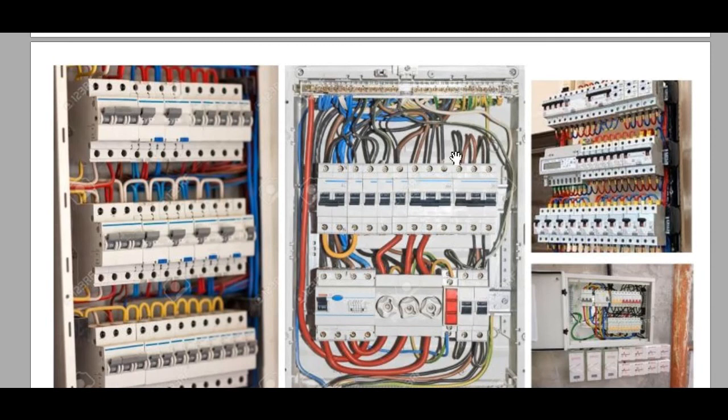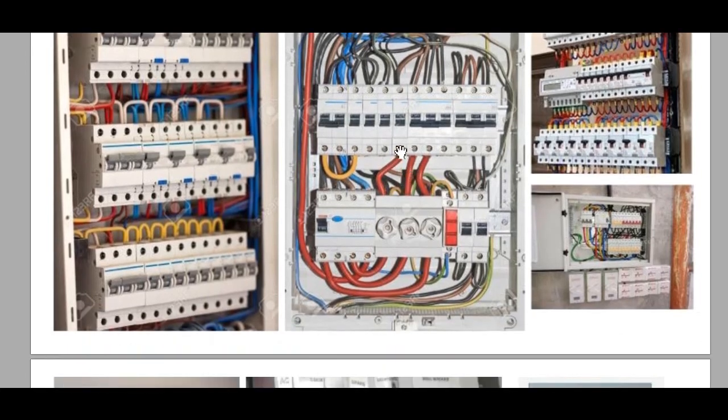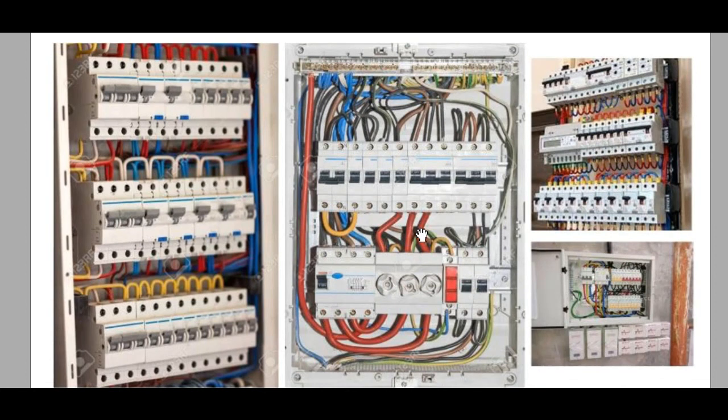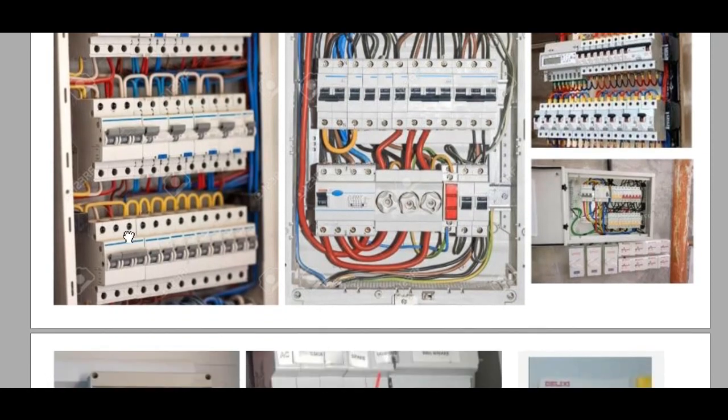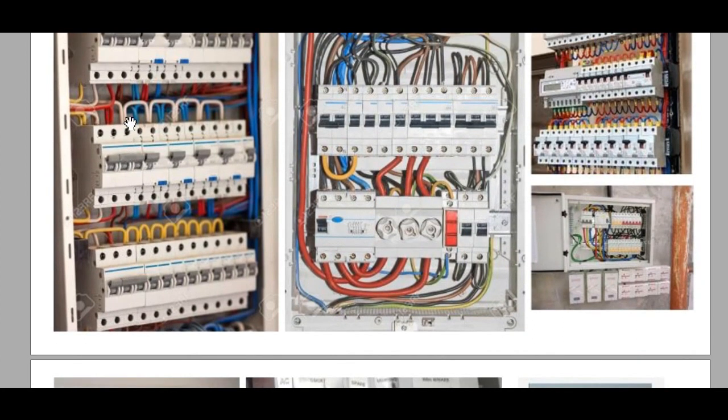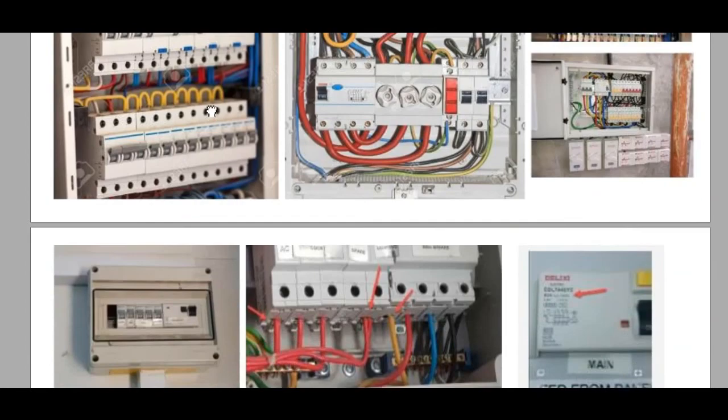They are here, but here we don't have numbering, we don't have tagging for the wires. Also, all the wires, they don't use bootlace ferrules. So here we have a punch list with a lot of items. While here everything is okay, but also they don't use bootlace ferrules. Plus there is no numbering for the wires, and also there is no tag to give you an indication for each wire where it is connected, and where the other end of this wire is going.